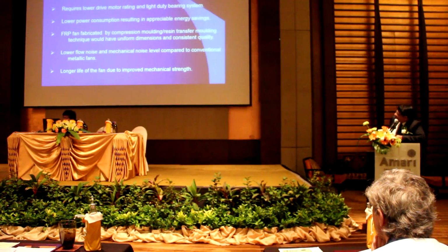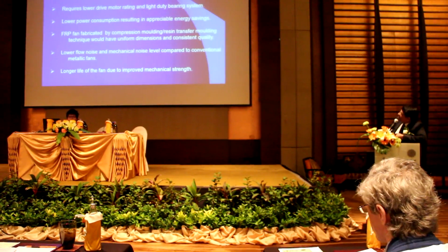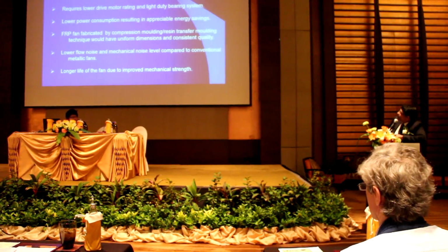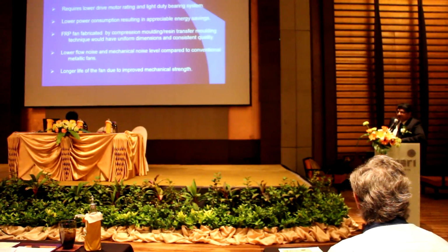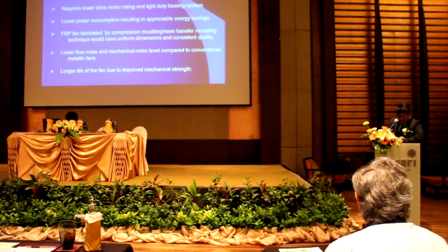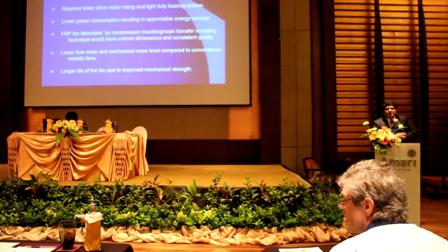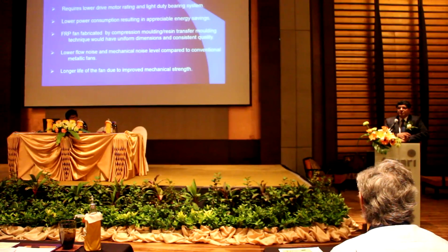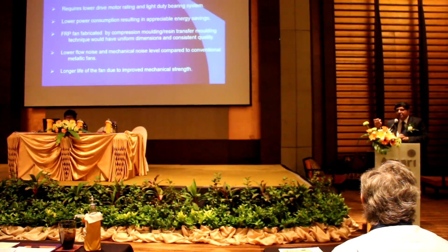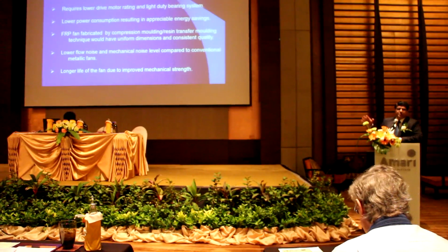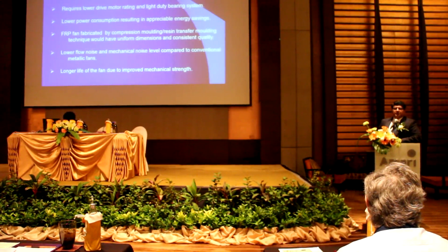Well, this I think sums up all. Optimal aerodynamic design of impellers to provide higher efficiency for any specific application. The reduction in overall weight of the fan. This is one aspect which I just want to touch upon for a minute or so. People think the energy conservation is possible because the weight of the blade is less. In fact, the weight of the blade has got no relevance in trying to have the overall energy conservation or reduction in the power. Okay?